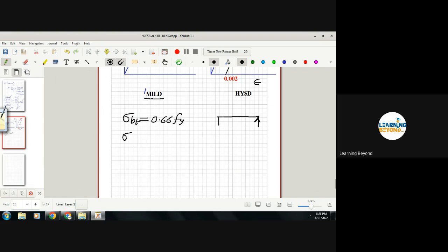and all of you know that in a beam there is a bending moment, and due to the bending moment there will be bending stress. What is this bending stress? Due to moment, it is M upon Z. At the bottom it will be tension, so bending tension, and this will be Z bottom. So if you are designing the section, you should take this permissible stress value, in Newton per mm square.